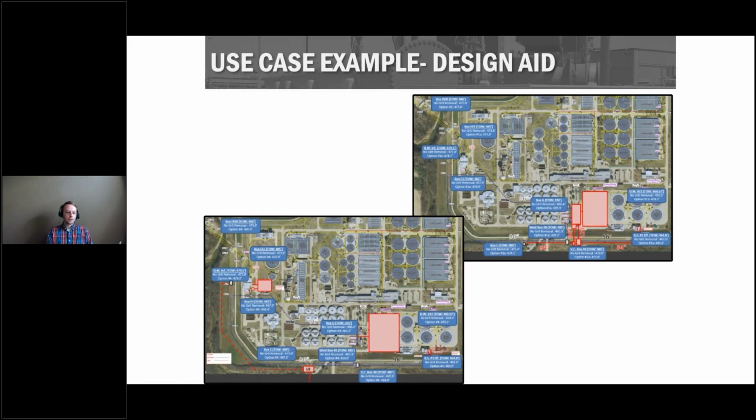We had some simple mapping, just calling out the existing no-grit scenario conditions with a grit option or alternative in service. And really what we were trying to figure out in this instance was, could you maintain gravity flow from one branch of the collection system, or were you going to need a lift station because the HGL as a result of the grit removal was going to be too high, and the collection system was going to have the potential for spills during wet weather events.